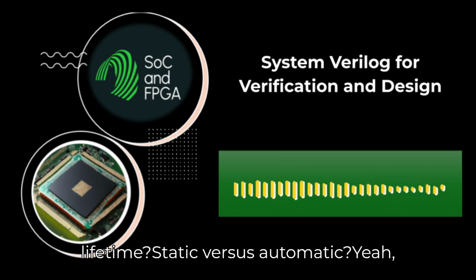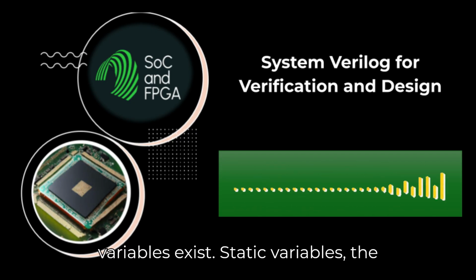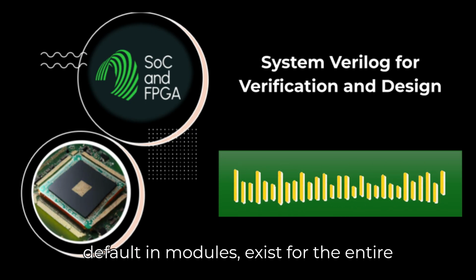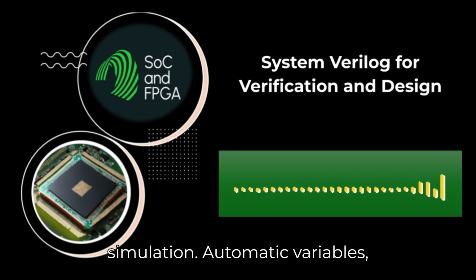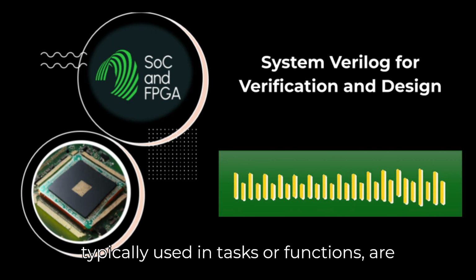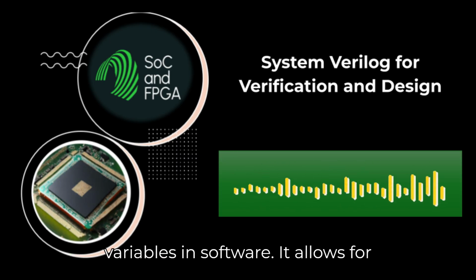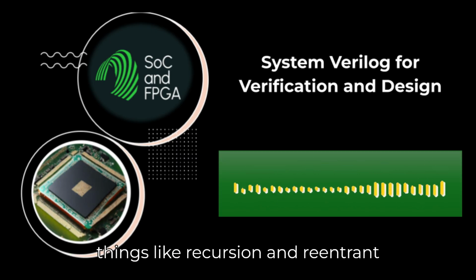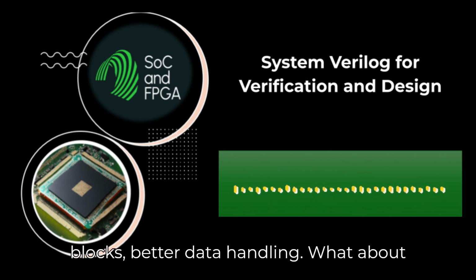What about data lifetime? Static versus automatic. Yeah, that gives you control over when variables exist. Static variables, the default in modules, exist for the entire simulation. Automatic variables, typically used in tasks or functions, are created when you enter that scope and destroyed when you leave. More like local variables in software. It allows for things like recursion and reentrant tasks. Okay, so more refined building blocks, better data handling.